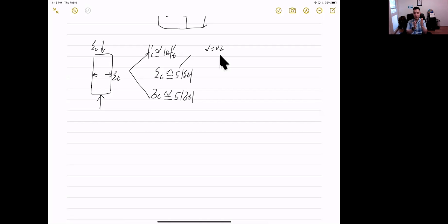The tensile stress will be much higher compared to its tensile strength, f'T. So that tells us the concrete will crack not under compression but under tension instead. That's why we see the concrete crack like this. This is because we have a tensile stress.